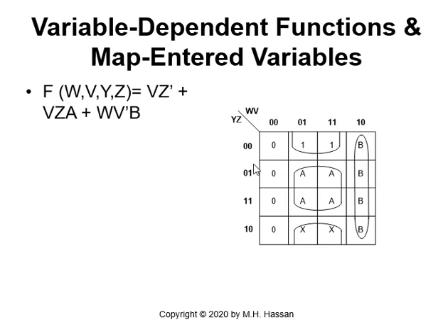And the function, we call it V, we did not call it X, so we don't get confused with the don't care X. So for V, W, Y, Z, what will it be? Those two ones, with those don't cares, are going to be a set of 4, and the 0 cancels W, and the 0 cancels the 1 for Y, so I have Z prime. So I have the first term, VZ prime, coming from those two and those two as a set of 4. The set of 4 for the A, the 0 will cancel with the 1, and the 0 will cancel with the 1, I have Z. So I have VZ multiplied by the value of A. Because if A is 0, this will go away. If A is 1, it will be Z. So the function is a variable dependent function that depends on A.